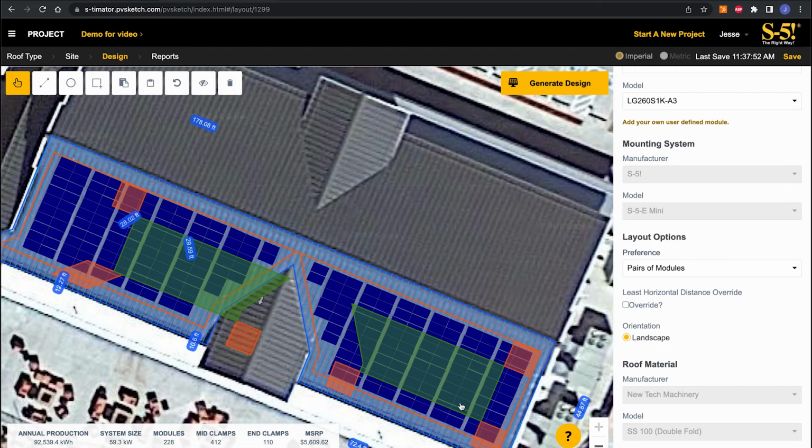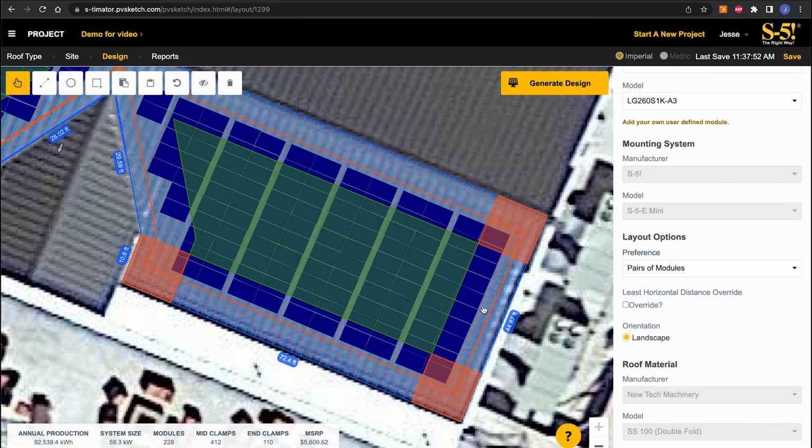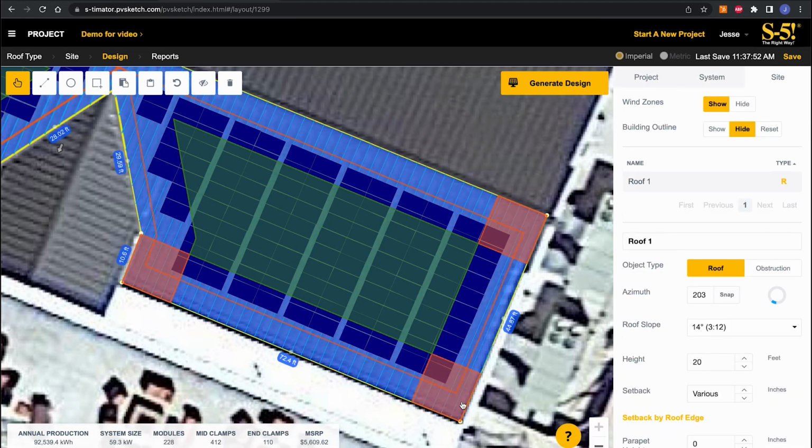For example, maybe this line I drew for the rake was not a 90-degree angle to the ridge, and this column was cut off halfway down because the setback interfered. Sure. You have full design ability at this point still. You can click back onto your roof, you can move your nodes around. In this case, I'm just going to put it back. But you can adjust, right?